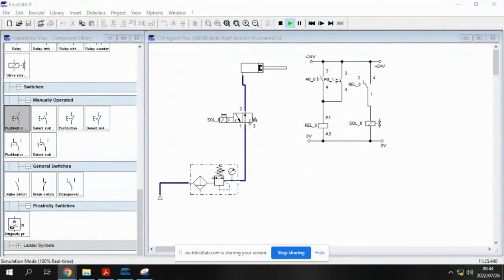And the reason why they use a contactor instead of a normal circuit breaker, you have to check with your electro or electrical guys. They will explain exactly why we should use contactors. But all I know is the contactors play a vital role in the era of automation, because you would want to send a signal to the motor, but you can't send it through a normal circuit breaker.